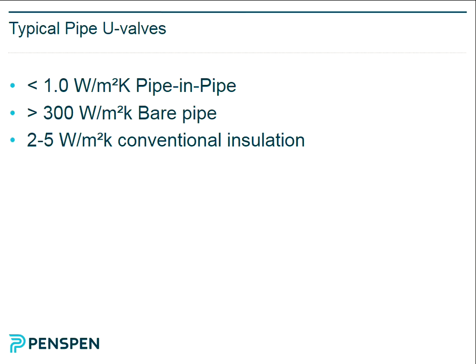This is an ITP, a proprietary product produced in France by an offshoot of Total, and here they use a screwed connection. They make a weld on the inner pipe, and then they screw the outer pipe together with a threaded and sealed connection. Logstor Rør is a Danish company. This is the Mallard field shell. Interpipe, this is the same company, but with ETAP, which stands for East Trough Area Project. And then some of the systems are actually reeled onto a reel ship as well.